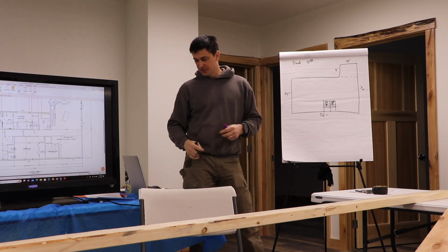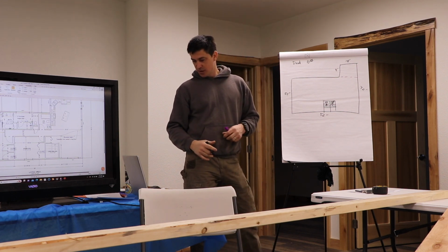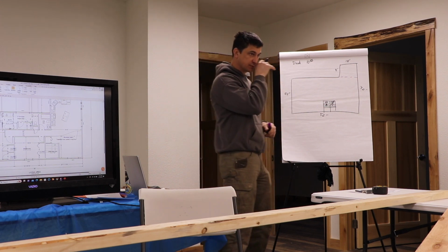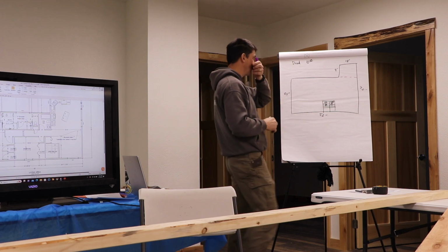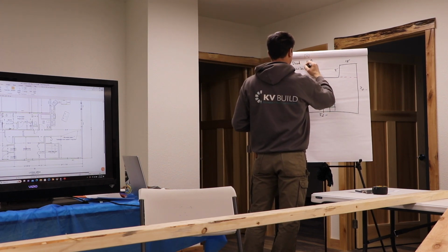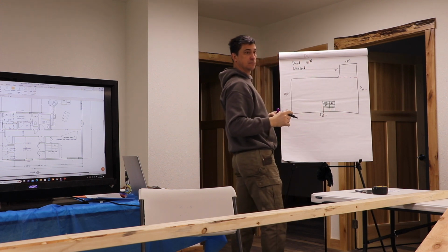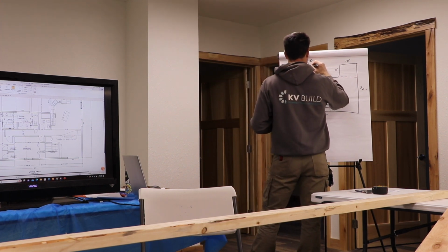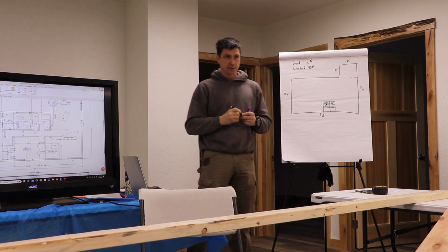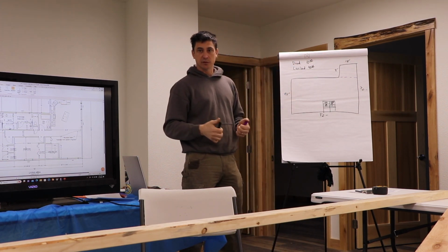Because it's pretty normal stuff, and probably not tile floors, carpet floors, whatever. So we're going to say we've got a 10-pound dead load. What do we have to do for live load? 40 pounds. 40 pounds, thank you. Code requires 40 pounds, whether we need it or not. And it's a pretty good number.